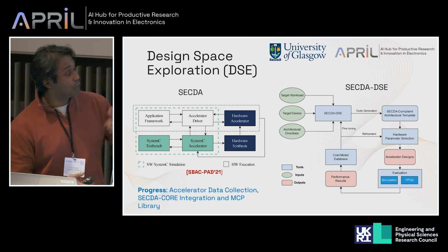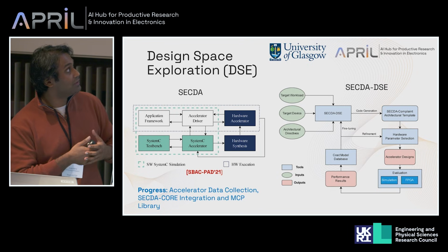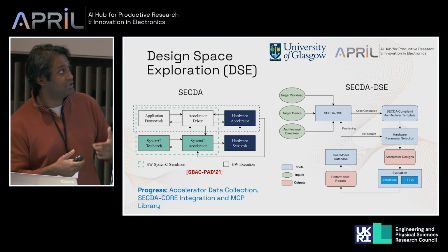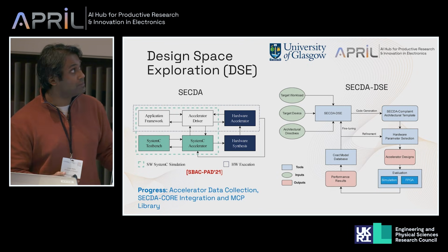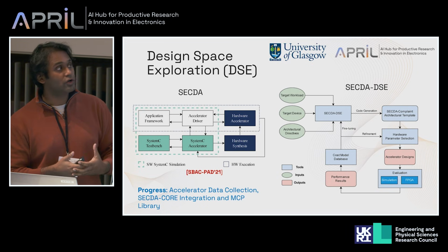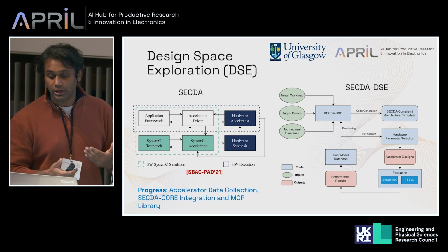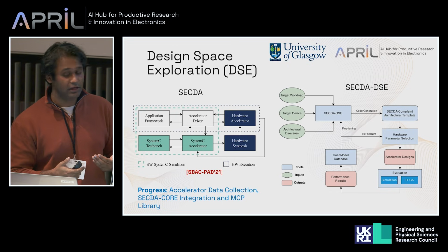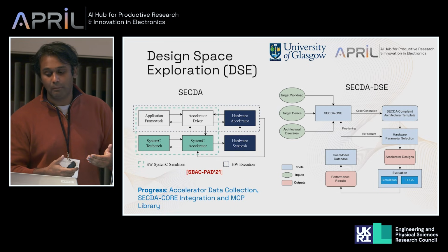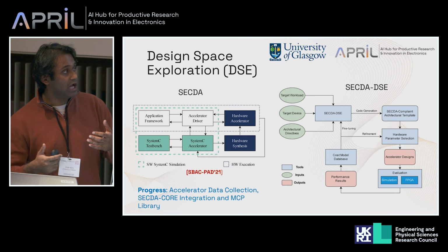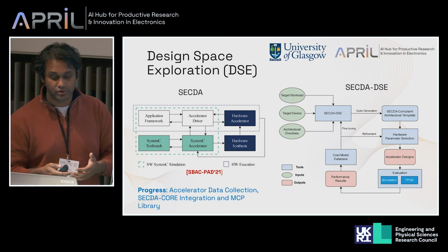With the designs, we go back to the SECDA design methodology where we do the simulation loop and the FPGA hardware synthesis loop. We get performance results. We feed this back into a cost model database that's used to update the SECDA-DSE tool. Again, this is an iterative loop where we improve our code generation and refinement stages by taking the results of both the simulation runs and the high-level synthesis and logic synthesis runs.